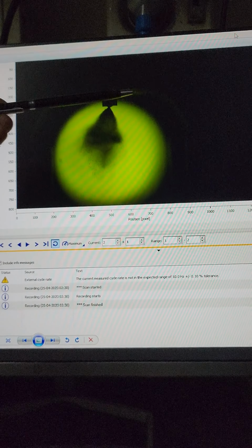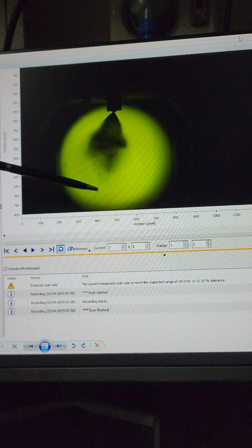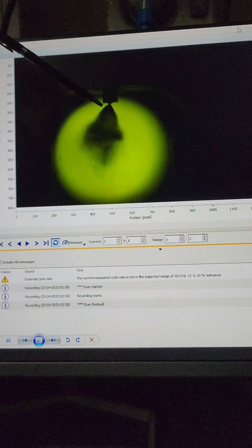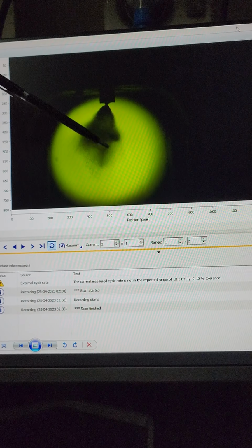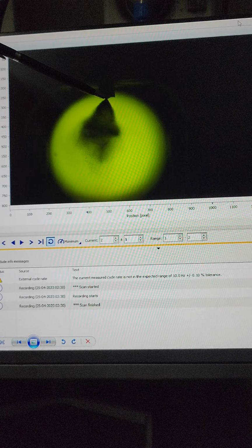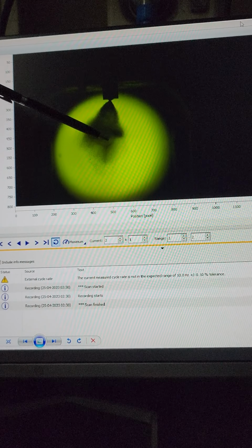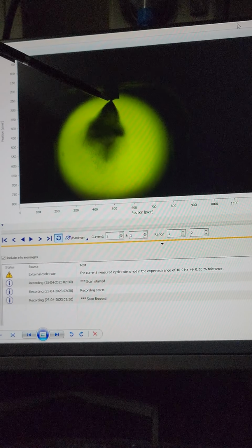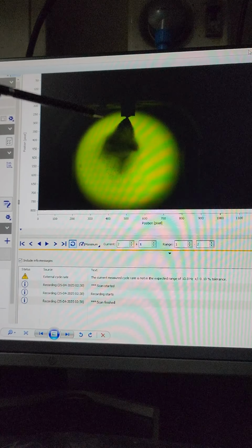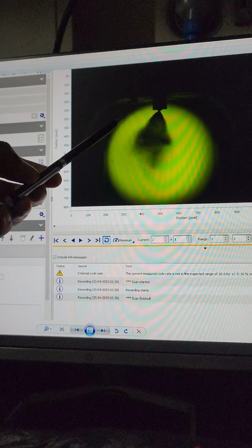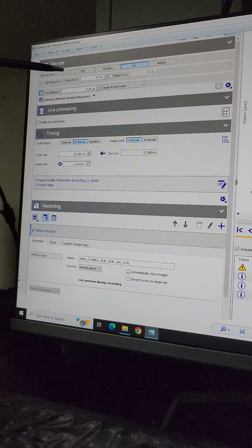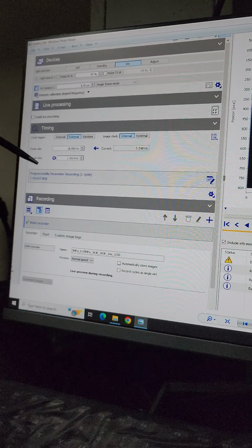At the time of post-processing, we have to extract these details and further characterize some aspects, like the penetration length, how far the spray is being developed from the tip of the injector, and the cone angle, the radial extent of this spray for a given instant. Now we can come to the different parameters, like what the controlling parameters are here.